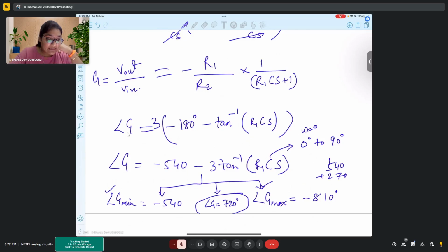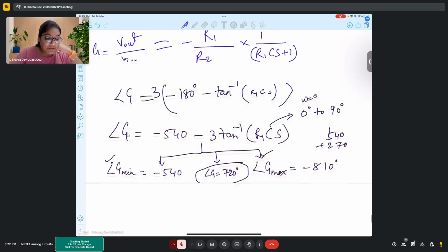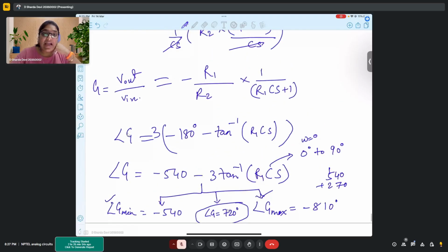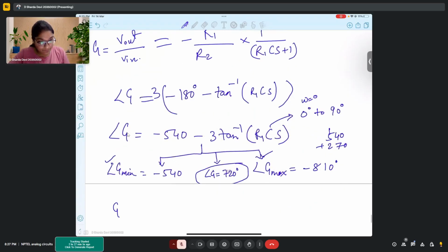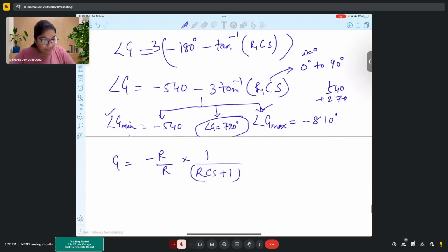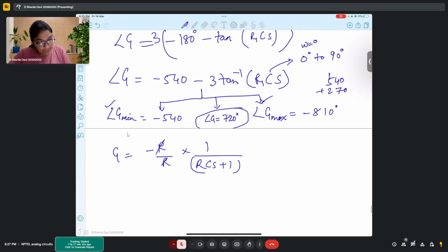Then, okay, so we are coming from the phase point of view, right? Yes, maybe phase. While calculating the magnitude, there might be some concern because of which the issue is arising. Is it possible, madam? Magnitude means output, or I mean gain may be 1 or 2. It depends. If you go with RC phase shift oscillator, then it will be minimum 29. And if I go with Wien Bridge, it will be 2 minimum.